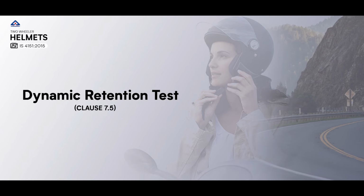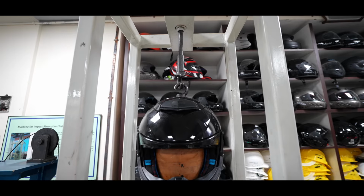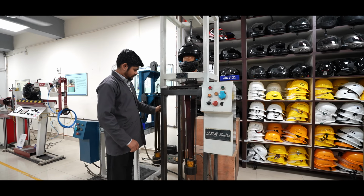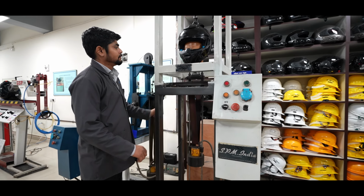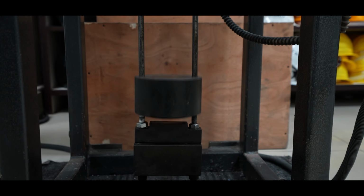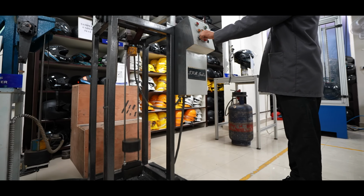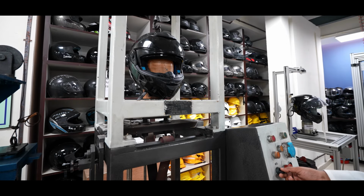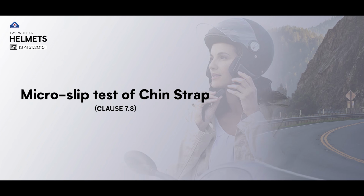Dynamic retention test, Clause 7.5. This test evaluates the elasticity of the retention system. A 15 kg load is applied dynamically to the straps, followed by an additional 10 kg falling mass. After the test, dynamic displacement is not to exceed 35 mm and residual displacement after 2 minutes is not more than 25 mm.